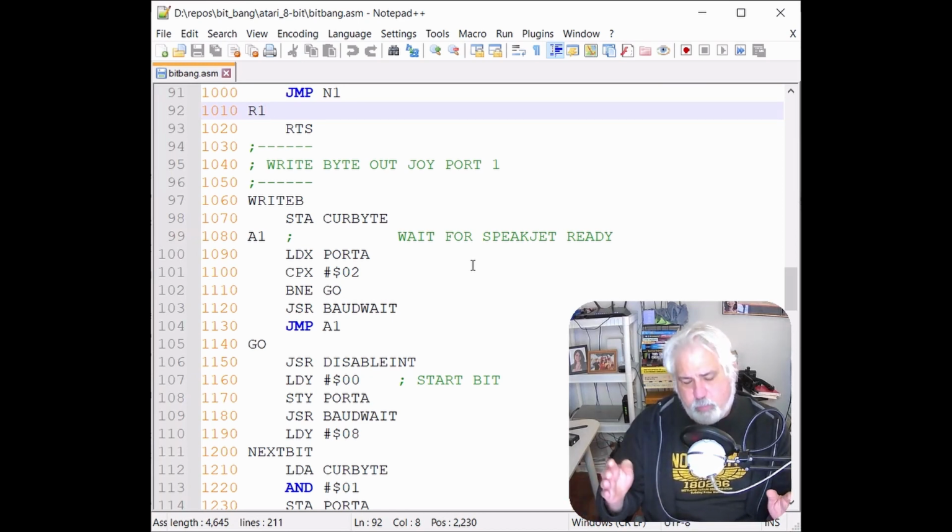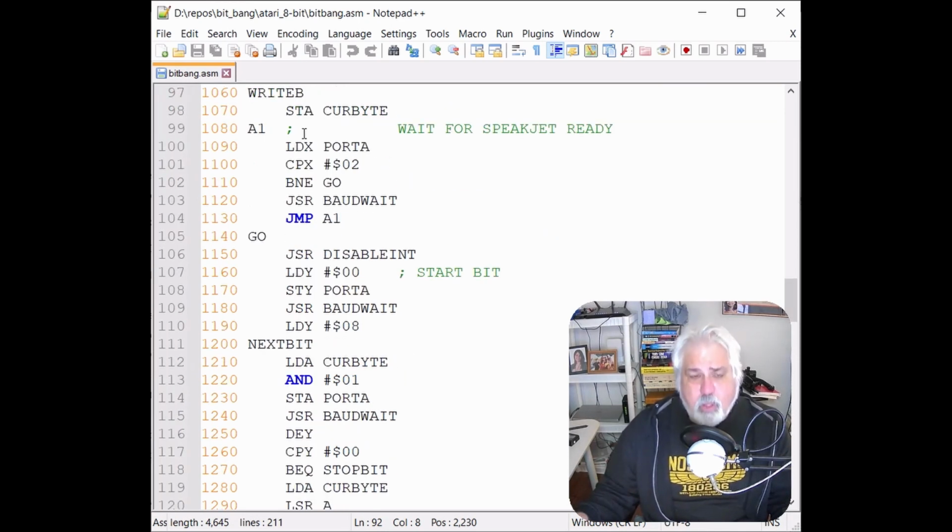So when you think about that data frame we looked at for RS-232, this is basically the start of that data frame. It is. In fact, the first bit of code here is just making sure that we're ready to send. It's a little bit of flow control. There's lots of different kinds of flow control, but the theory is that the device you're sending to can tell you, hey, hold up, slow down, I need you to wait, and this allows for that.